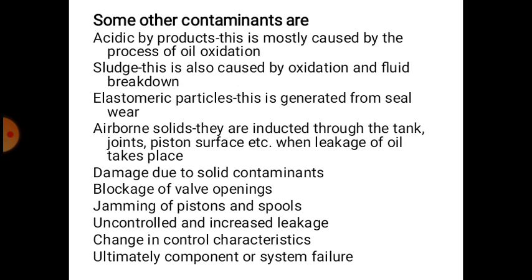Damage due to solid contaminants. So what are the damages caused by the solid contaminants in the hydraulic system? Blockage of valves. There may be blockage of the valves due to the contaminant solid particles which are present, so it will stop or slow the oil flow.